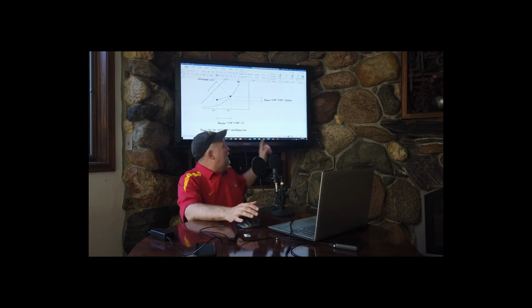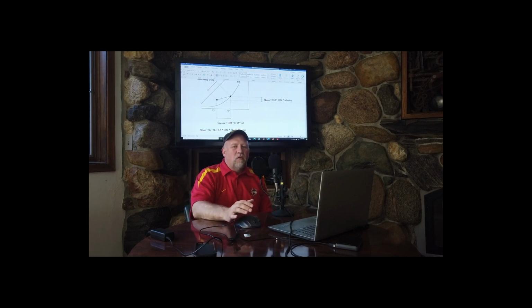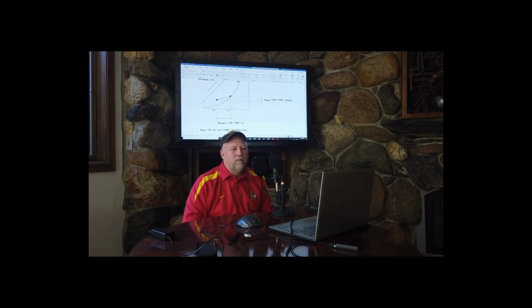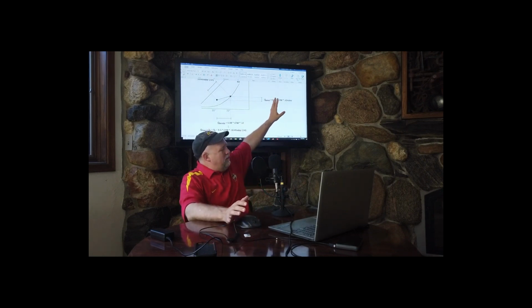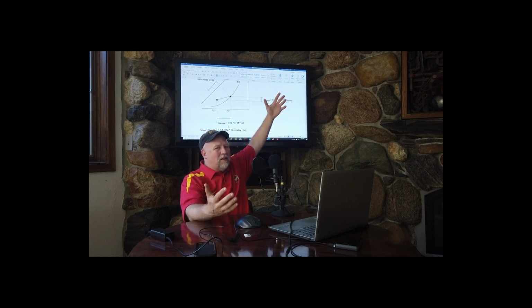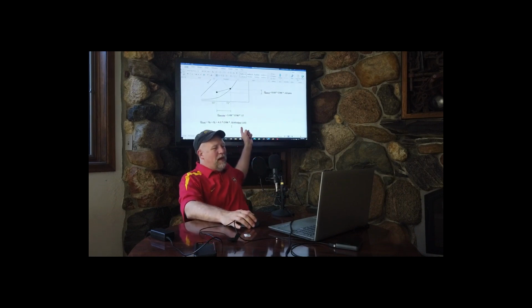4.5, just like the 1.08 and just like the 0.68, those are all merely constants that make all the units work out. Cubic feet per minute times grains does not equal BTU per hour, right? The 0.68 works that equation out. It's a constant that makes the math work. Same way with 1.08 CFM times the difference in temperature.